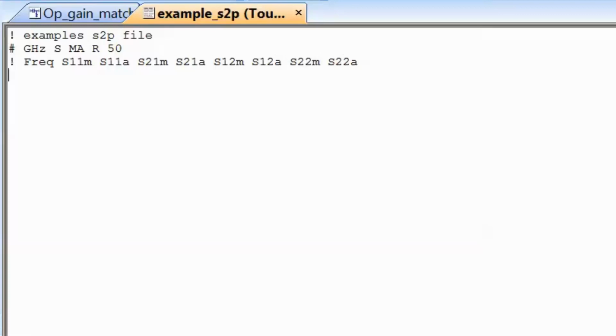Then you can just type your s-parameters in, but first of all you have to write the frequency to which this s-parameter set corresponds. So for example, if at 1 GHz our S11 was 0.2 and had an angle of 120 degrees, this is what we'd write. Then we'd write the S21, which is say 2.5 with an angle of 40 degrees. Then we can write our S12, 0.02 say with an angle of -30, and then finally the S22, say 0.6 with an angle of 45 degrees.